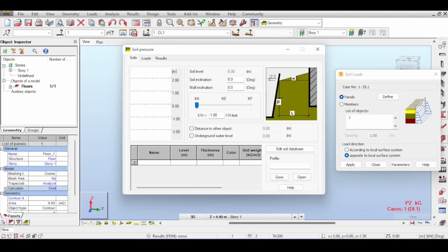All right, fantastic. Now I need to start defining my soils. Now there are two options. The first option is that you use the soil templates characterized here. The second one is to use your own soil. So you can basically call, for example, here my own soil. Say the level of my own soil is at 3 meters because, well, the retaining wall is 3 meters high. For example, the unit weight of my own soil, of course, now is where your geotechnical skills and your geotechnical lab report comes into play.